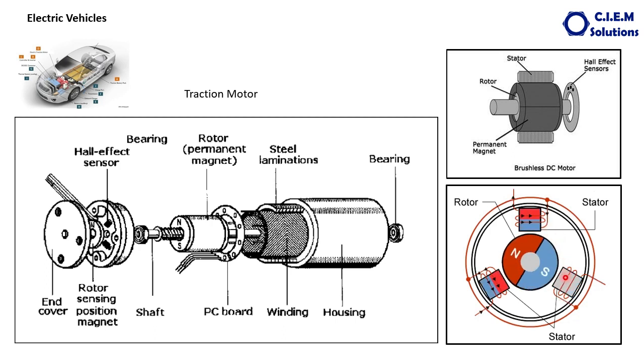The next pole is electromagnetized, it will be pulled like this. In the same way, this pole is magnetized, it will be pulled like this. The repulsive and attractive action of the magnetic poles makes the rotor rotate. All the motors are bidirectional, so they will rotate in both ways, clockwise and anti-clockwise, depending upon the driver's requirement.